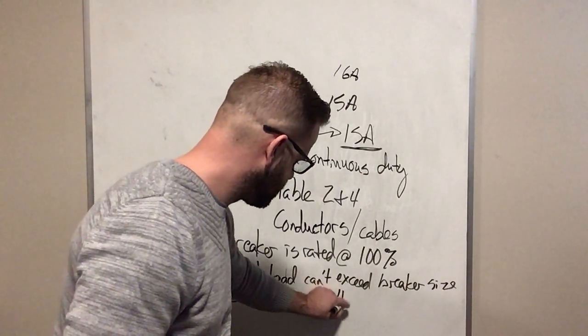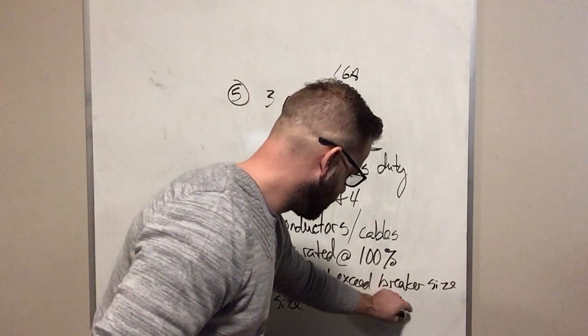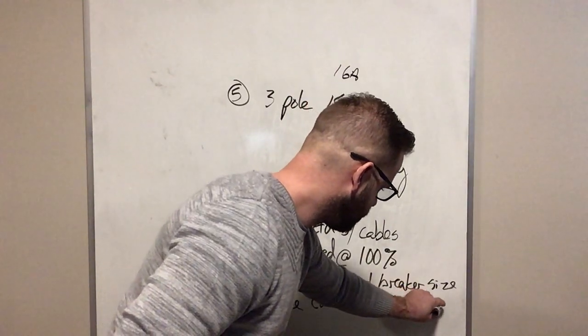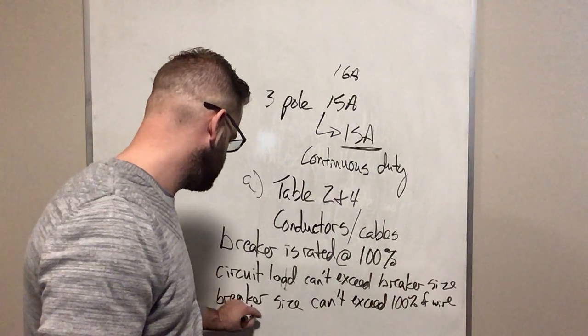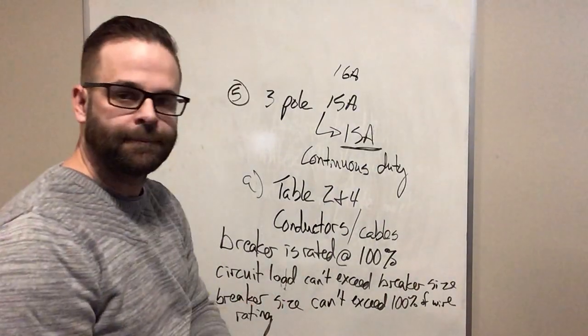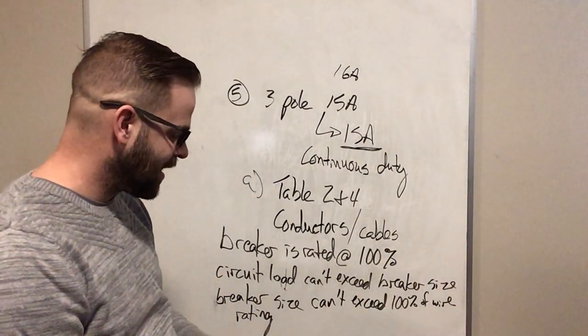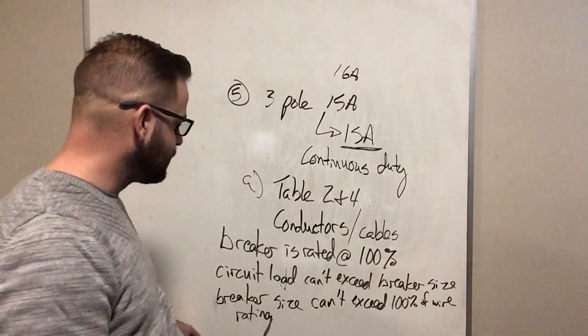can't exceed 100% of wire rating. Okay, so just write that blurb down. So breaker size can't exceed 100% of wire rating. So you're fully protected with that.